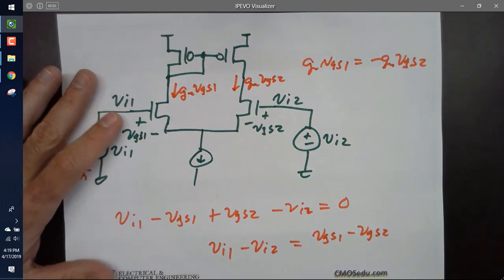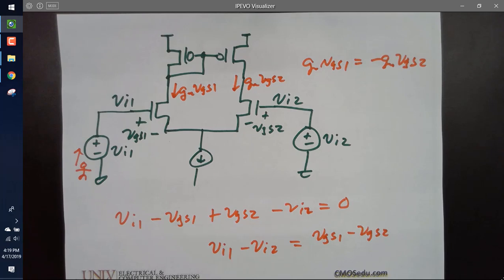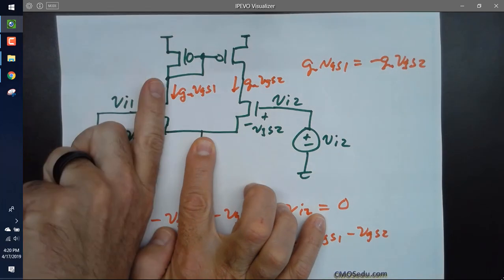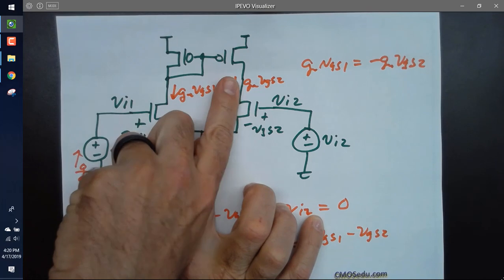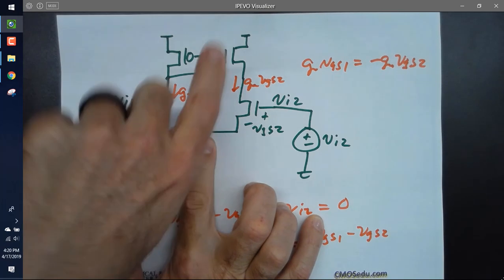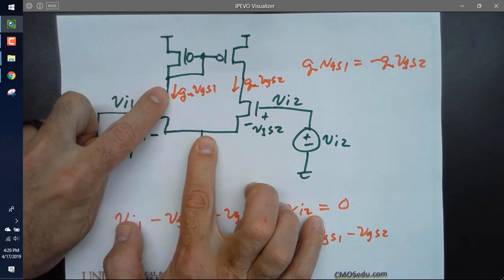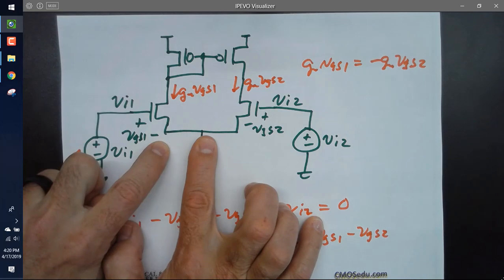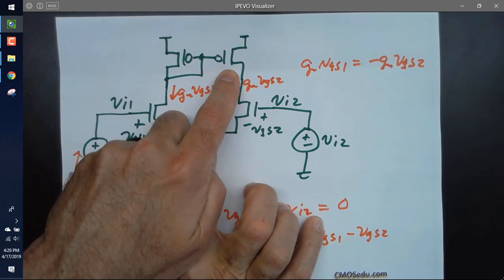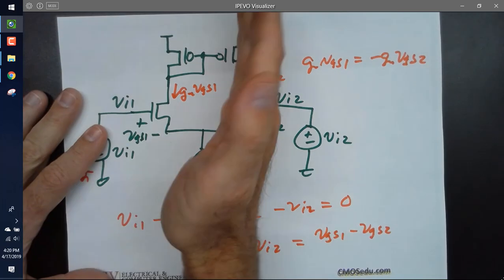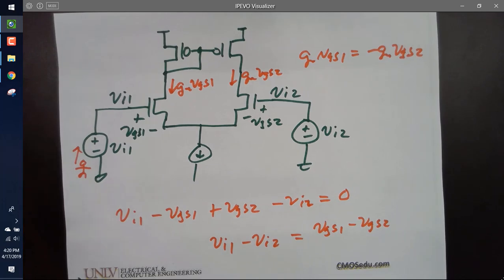Give me an explanation why. Because no AC current's going to flow down there. Yeah, so the overall current here goes up, the overall current here has to go down. When the overall current here goes down, that's the same as it being a negative AC current. So if this current went up by a microamp, this would go down by a microamp. And so I'd say the current here is minus 1 microamp, or positive 1 flowing opposite of the arrow. That's really clear to me, but is it clear to you?